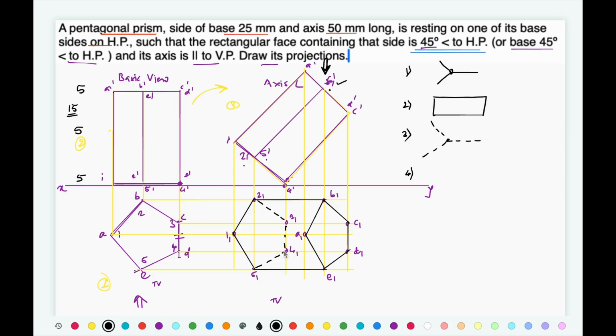So those three I will draw first with dotted lines. Now according to rule number 3, if you look at corner number 3, 2 3 and 3 4 are dotted lines. So the third line starting from that corner, which is going to connect it with the point C1, is going to be a hidden line. Similarly at the corner, two existing lines are dotted, so the third line starting from that corner is going to be a dotted line.